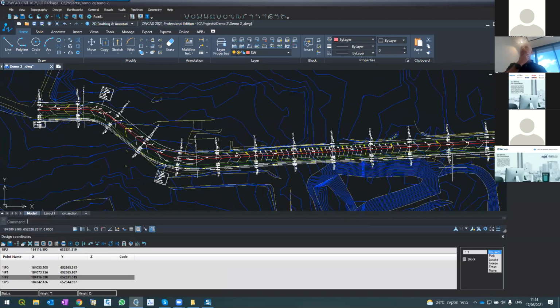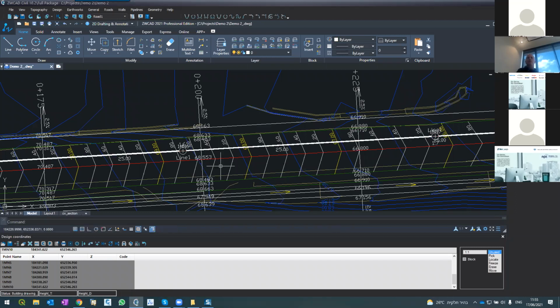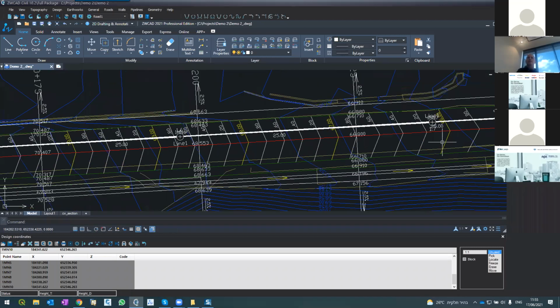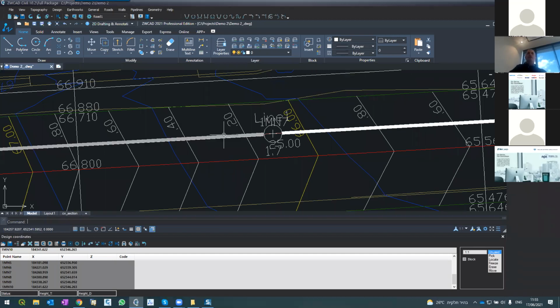And go to the layout, so in pipeline number 1, and select it. Sorry, not this one, this one. Now, like we did for the road, now it became a pipeline, and all the coordinates of the manholes were created here. So if I apply, automatically the system will convert it into a pipeline. So you can see each manhole with the pipeline. For now, the system used default settings.